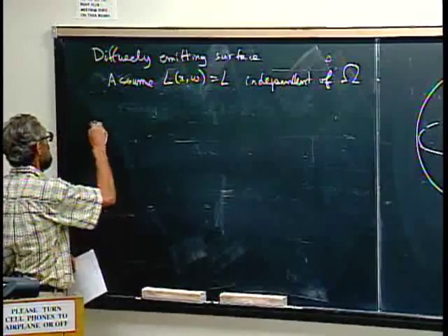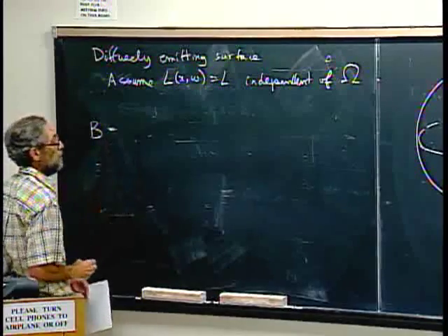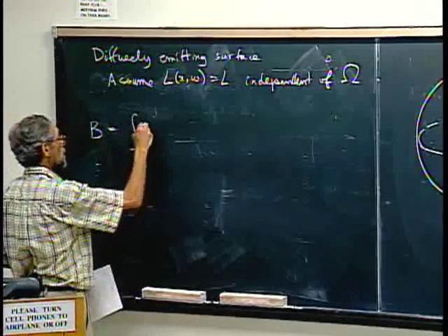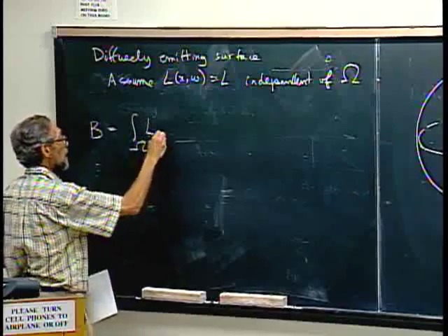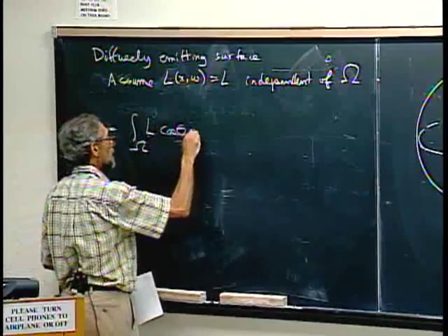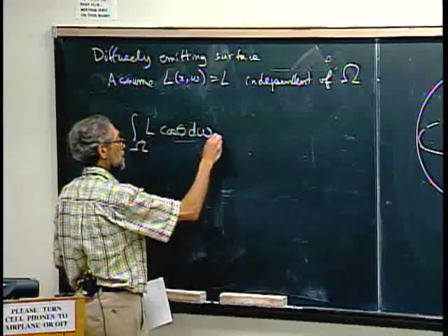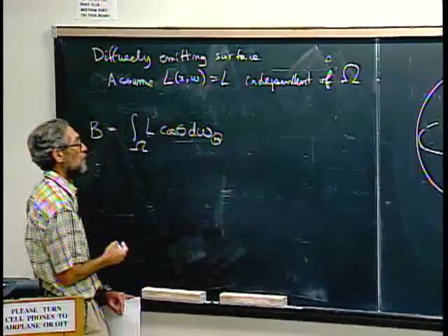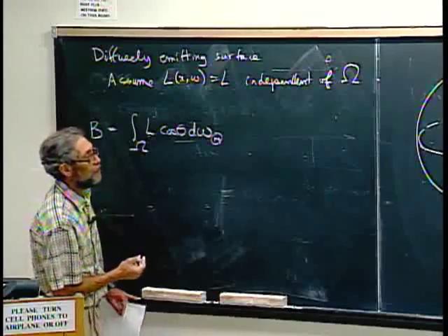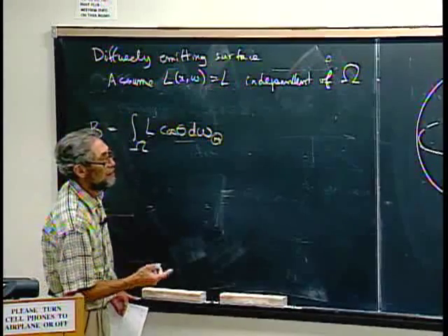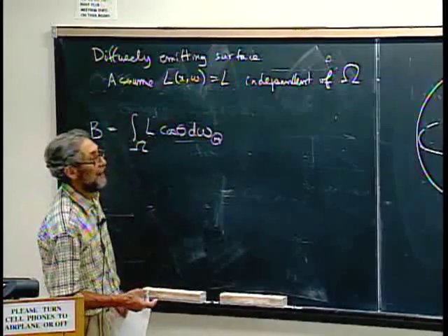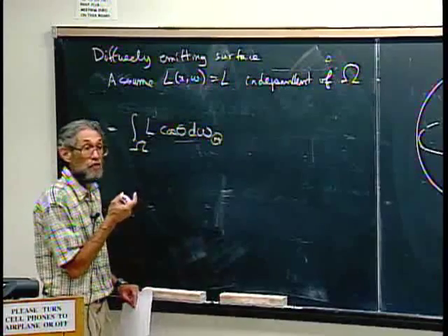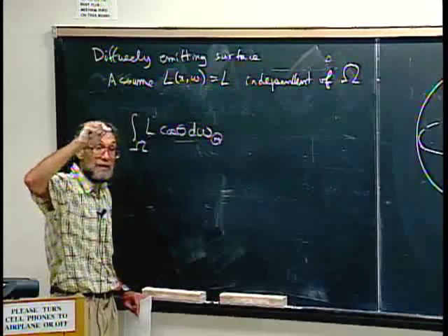And then if we want to compute the radiosity from the surface just from that brightness, my integral is now the integral over the hemisphere of just constant L times cosine theta d omega, of the solid angle leaving on the unit hemisphere. And now, if I haven't erased it, what I need is my formula for d solid angle. That dA on the surface is really my d omega, a small solid angle with a d theta and a d phi.